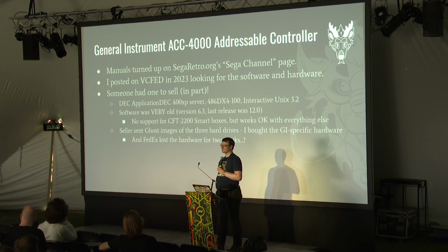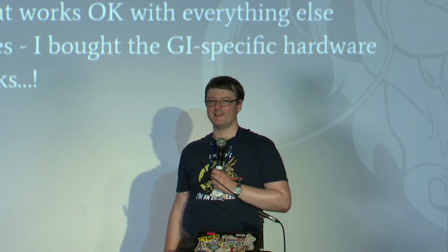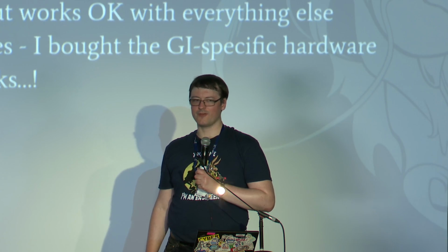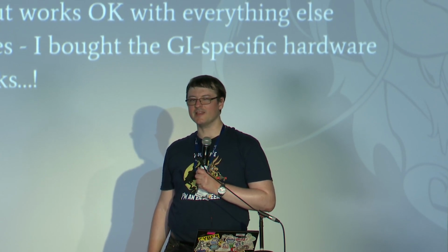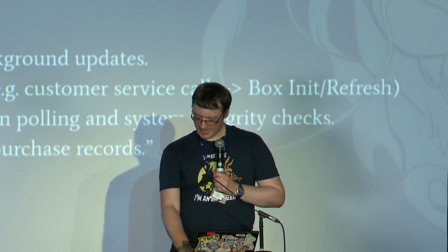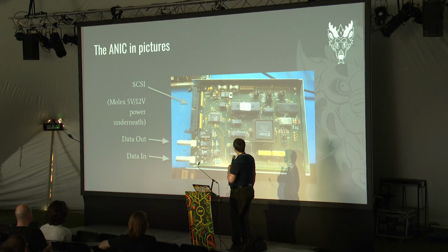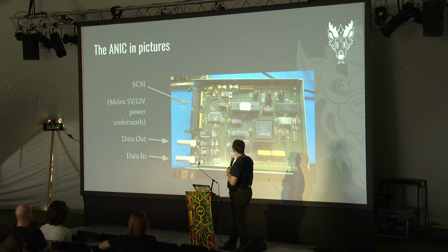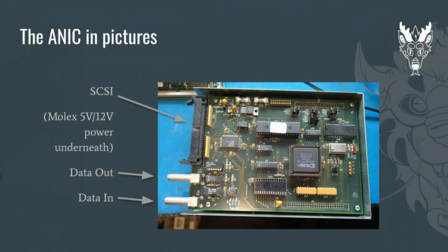with some extra fancy bits. It's got a lot of serial ports. The standard configuration was 8 serial ports. It had a tape drive for doing backups, but the interesting part of it is it's got a second PC inside of it, which is this little thing. That is called an ANIC, Asynchronous Network Interface Controller. There's a data in and out port that has biphase encoded RS-232 data with some command packets flying around on it.